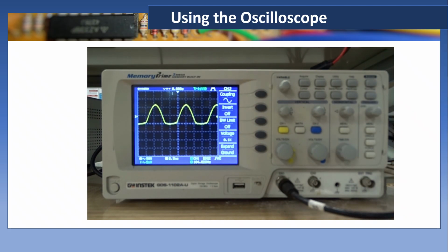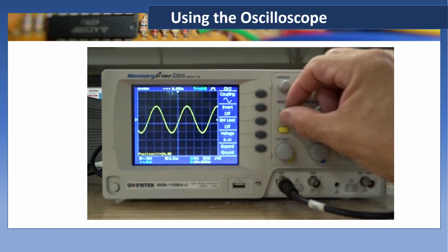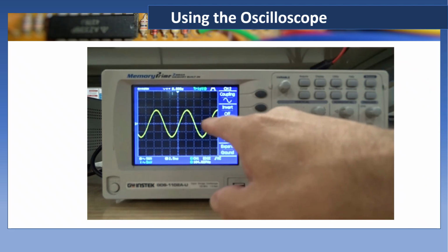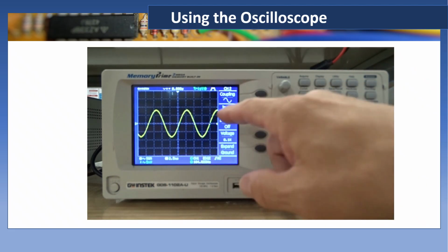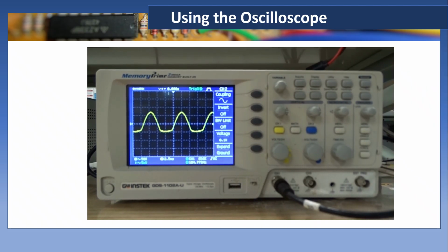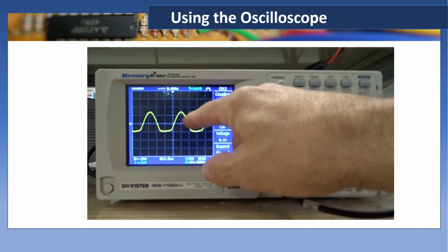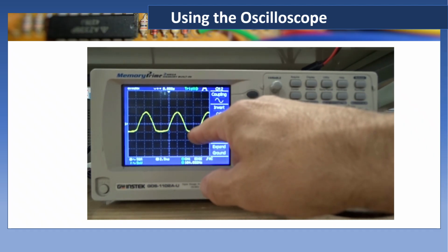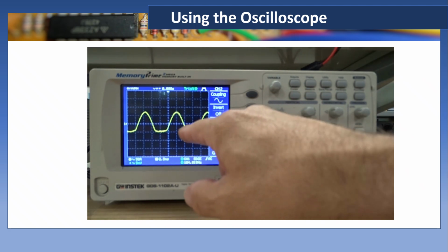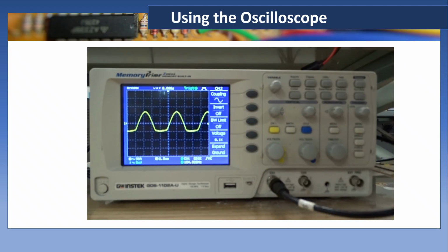so if I take that off, you can see I'm no longer centered. So ideally you want that line there, which says the 1 on the outside, on the center of your crosshair. And that gives you a more accurate image of what is taking place. Notice that if we have 1.5 squares up, we're actually chopping off the top half of that waveform. It's not coming down to the 1.5, so we're chopping off the top half of that waveform from our diode setup.